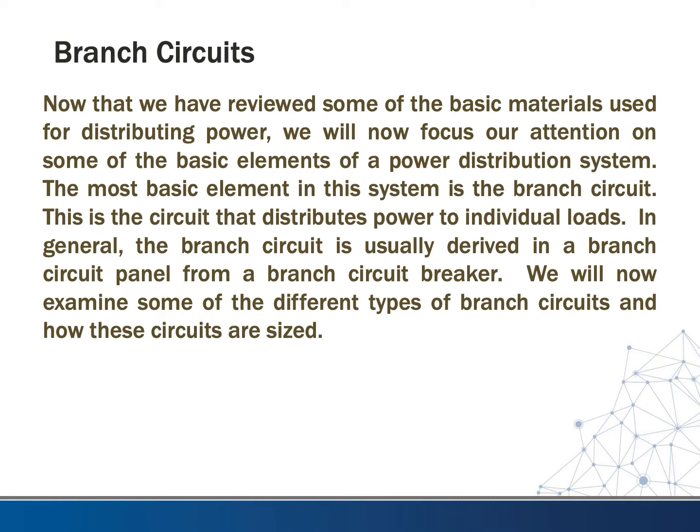Now that we've reviewed some of the basic materials used for distributing power, we'll focus our attention on some of the basic elements of power distribution systems. The most basic element in the system, of course, is the branch circuit. This is a circuit that distributes power to individual loads. In general, the branch circuit is usually derived in a branch circuit panel from a branch circuit breaker. We'll now examine some of the different types of branch circuits and how these circuits are sized.